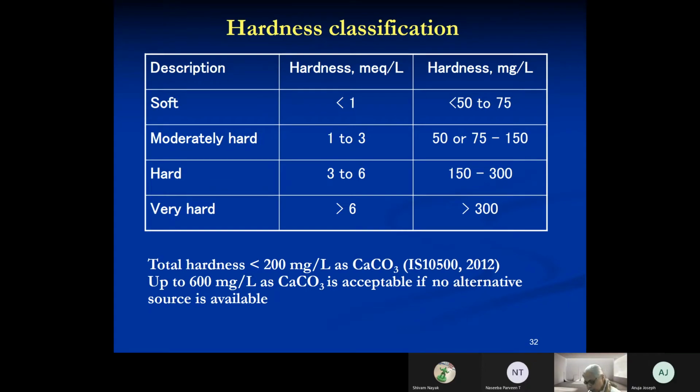Now, remember that hard water is not suitable for drinking, even it tastes bad. So it has a brackish taste to it. And also, like I said, it's non-toxic. So toxicity is not an issue. What is an issue is a commercial impact. So you have the soap problem, the cleaning problem, and you have the scale formation. So these are the two issues related to hardness. Now, based on hardness levels, we can classify waters as soft water, moderately hard, hard, and very hard water.